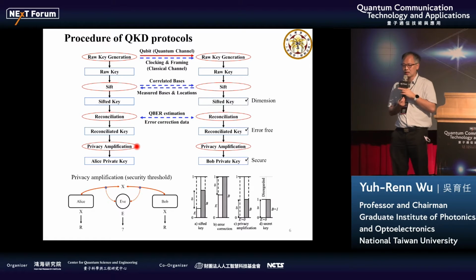So instead of just understanding the device, how it entangles, or the detector efficiency, actually when you put all the components together, you will find that when you send 1 gigabit signal, at the Bob side it can only detect like a kilohertz signal. So you lose 1 over 1,000 signals. And you don't even know if the signal you detect is real signal or noise. So that's something you need to be aware of before you start to do quantum communication or quantum computing. Especially in photonic based systems, you'll find that they are quite noisy.